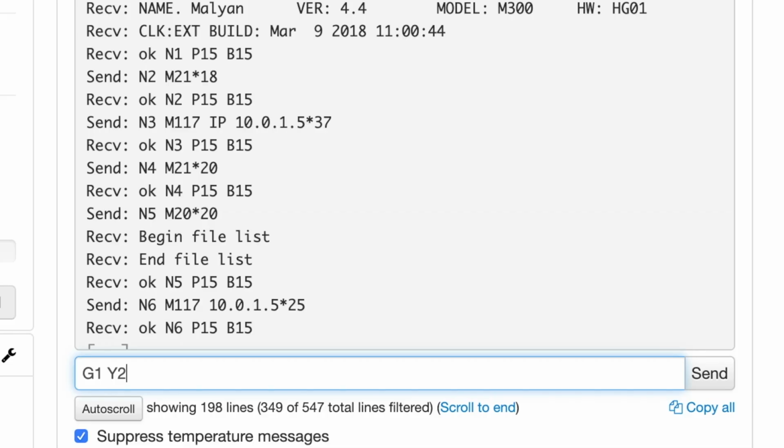Okay, I've power cycled the printer, I've re-leveled the print bed, I re-homed it to the center, and now we're going to try the command again, and this time I won't drive the print head off the surface. So we're going to do a G1 Y20 this time. We'll make it Y30, extruding 0.5 millimeters of filament. And that's exactly how it would work.